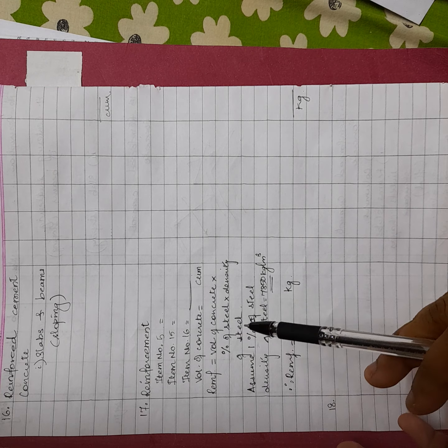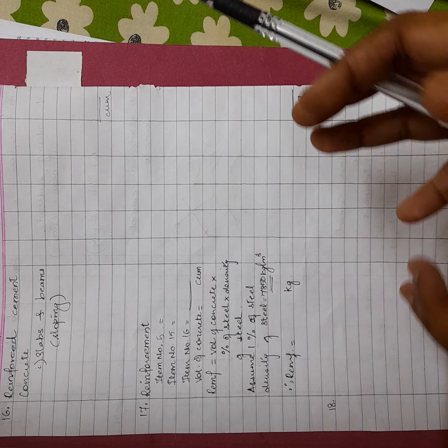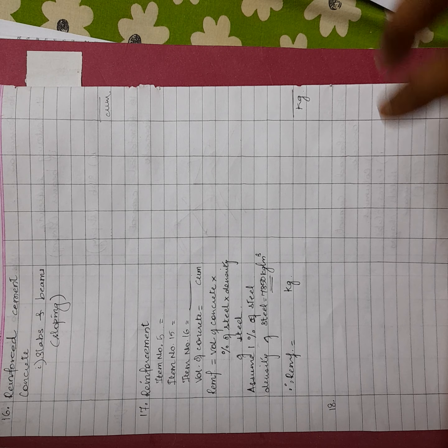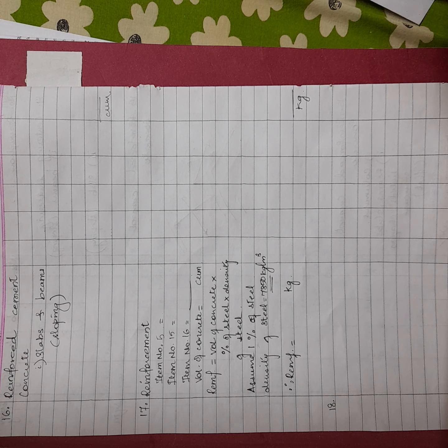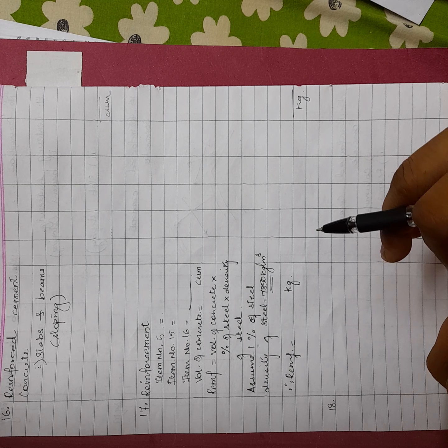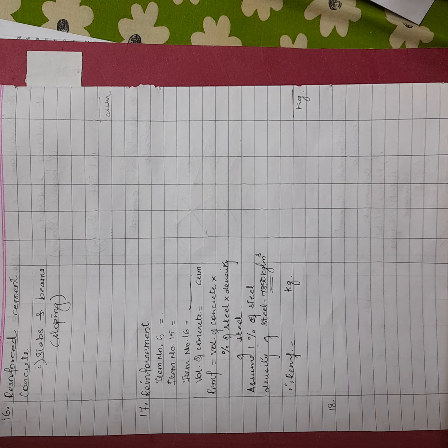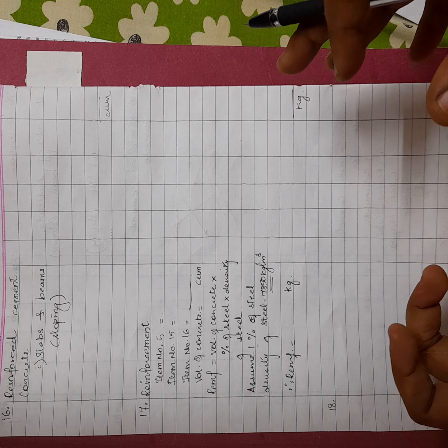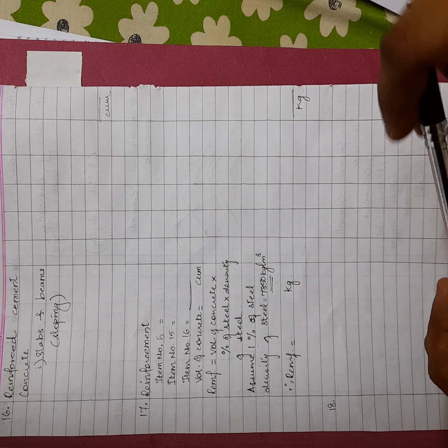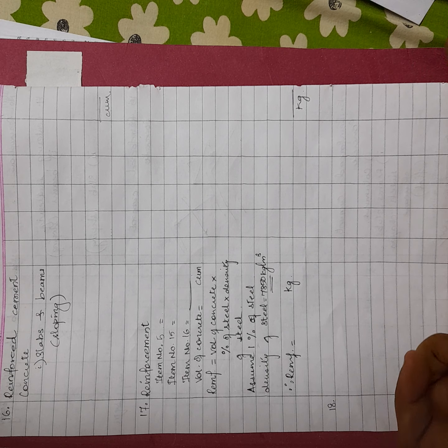Now this value varies from 0.8% to 1.5% depending on how the structure is. If the structure is very simple, you can go for 0.8 percent also. If there are retaining walls, swimming pools on top at the terrace level, or a terrace garden, or some complications like a high design building, for those types of buildings you can assume a percentage of steel even 1.5.